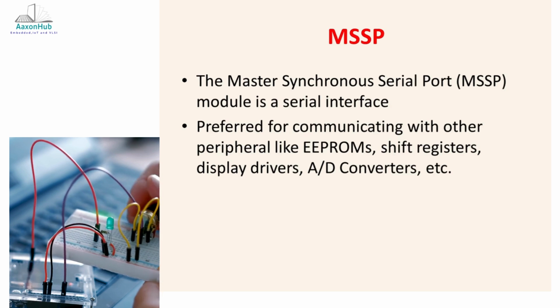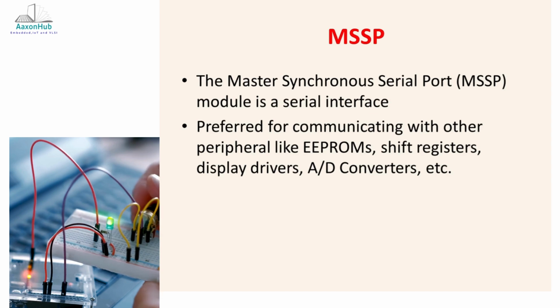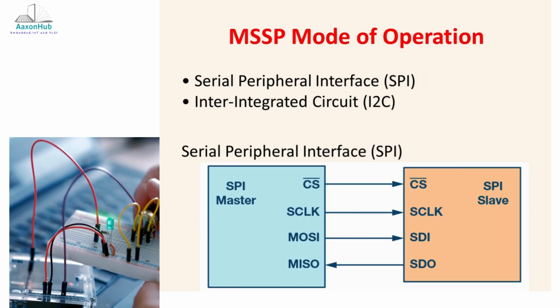MSSP in PIC 18. MSSP is Master Synchronous Serial Port. In PIC 18, this MSSP is a serial interface useful for communicating with peripherals or microcontroller devices. These peripherals may be in the form of EEPROM, shift register, display drivers, A to D converters. This MSSP can operate in two modes of operation.